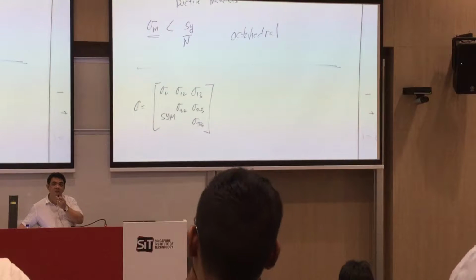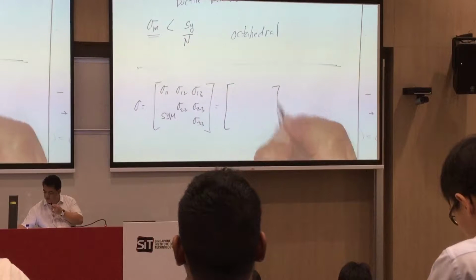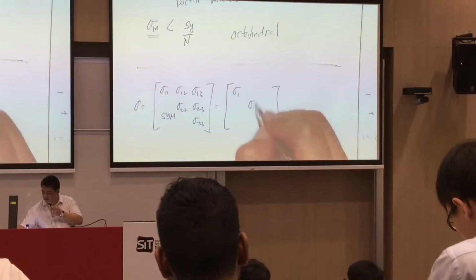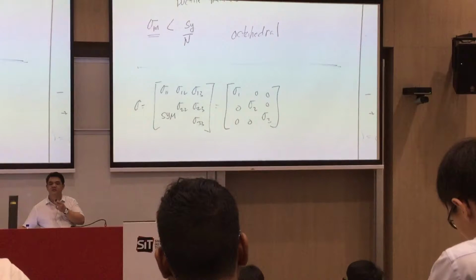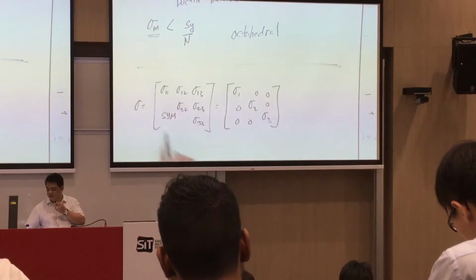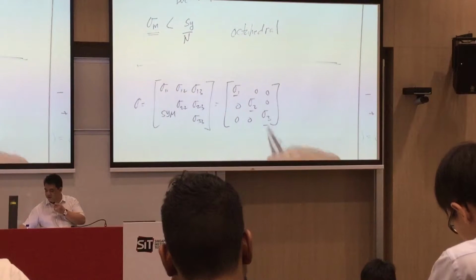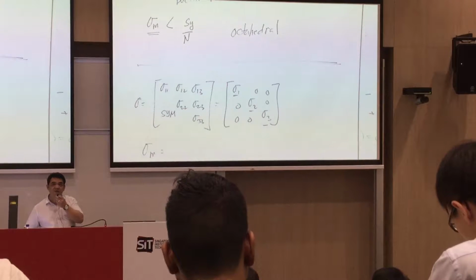We have proven this one. Okay? And then this one will be equal to, just do a transformation so you can get your principal stresses. Yes? So that's how you get this one. Of course, you get sigma 1, sigma 2, sigma 3. Also by using this one, you will be able to solve for your von Mises.